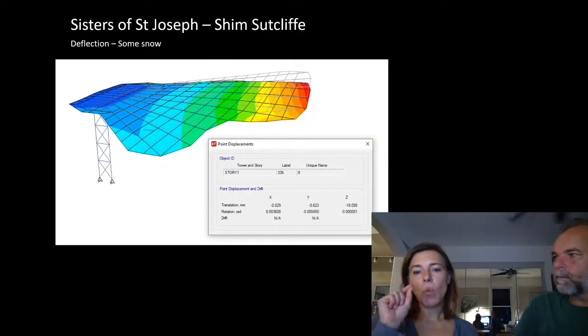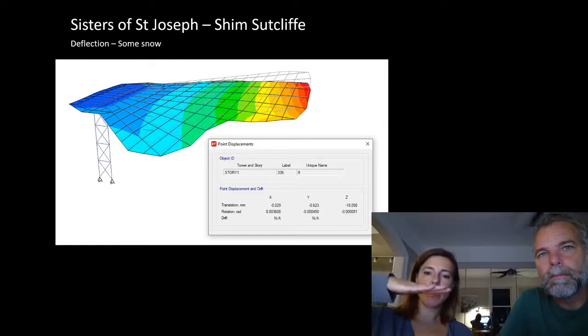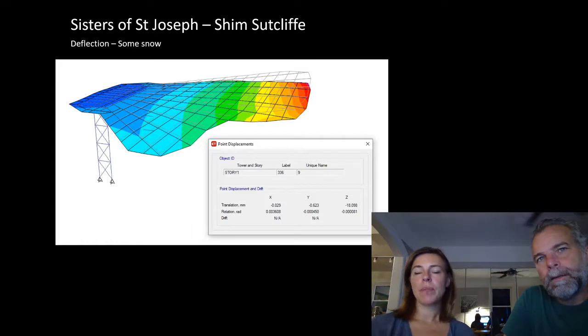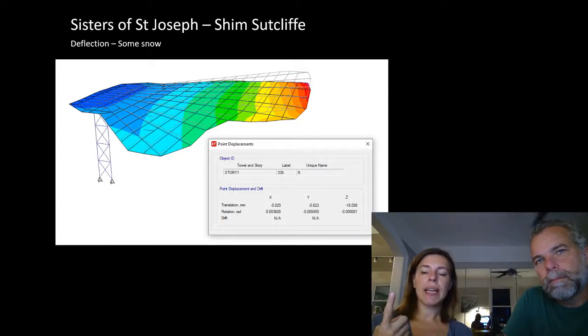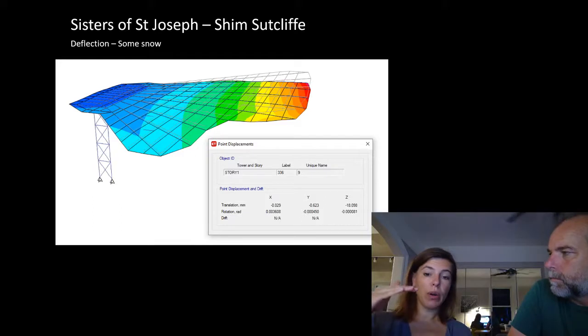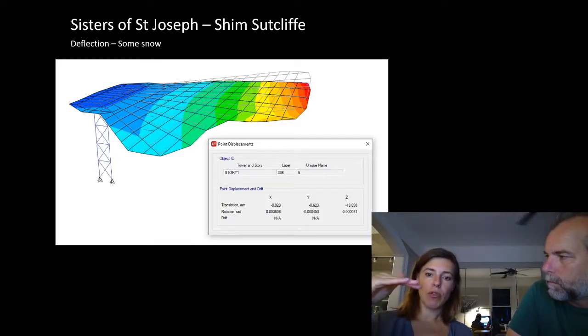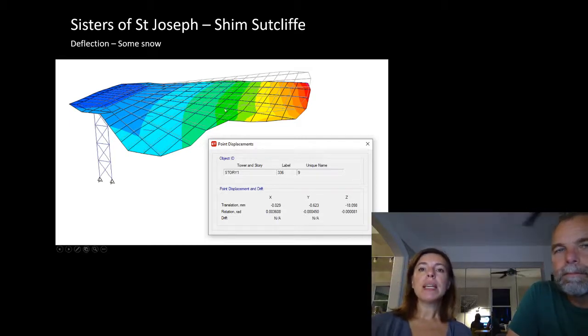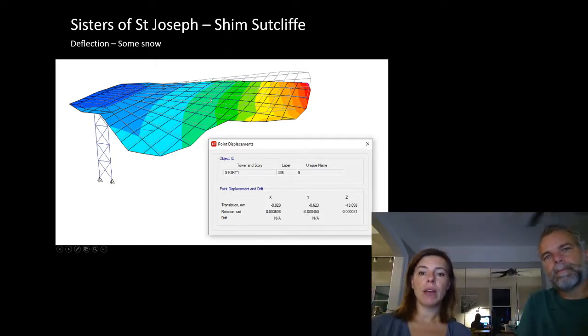So I'm going to add one more slide into this, and this is the image from above, where I was inside the building looking down at the top of the canopy. The fabricator was very careful to do all the welding on the top so that any distortion of the member would be less visible from below. So we're welding this plate steel, so the visual implication is less from the bottom than it is from the top. But even still, the welding of it caused some distortion. And from the top, you could see a little bit of water standing in the locations.